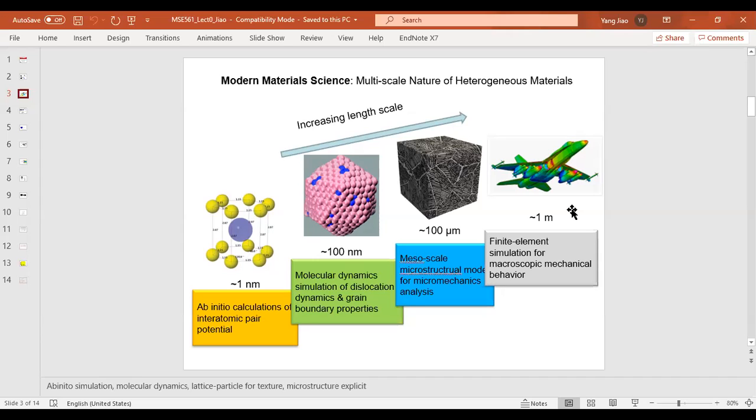We're interested in knowing the stress distribution of this airplane when it's in service. And this color map shows you, for example, the stress, roughly speaking, of different parts of the airplane. But we want to know and we want to make sure that during the service, these hot spots are going to be safe, right? After how many times of usage, we still want the material to be reliable. And the performance of these materials is determined first by the grain microstructure.